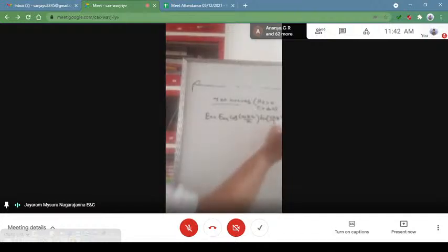Those things I won't always write because they are implicit. The field not only varies with respect to distance, it also varies with respect to time. Both are to be incorporated. With respect to distance, whenever a wave has to propagate, alpha should be 0 and beta non-zero, so that the exponential function contains only the phase constant among the propagation constant of the waveguide system.